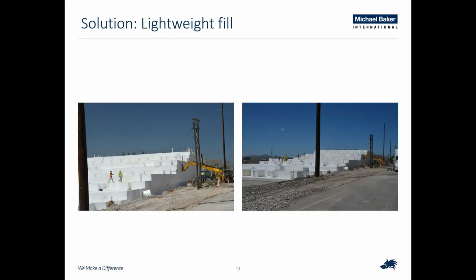This shows the geofoam embankments. So shifting the alignment helped mitigate those utility relocations, but the tall walls with ordinary fill would induce settlement on the adjacent existing utilities. And so geofoam approaches were proposed and designed for a zero net load, thereby eliminating the concerns for settlement on the existing utilities. And for those who don't know, geofoam is essentially just engineered styrofoam. It's very lightweight. And the zero net loading on the existing soils was accomplished by excavating out some of the soil that was there and thereby replacing the heavier soils with this lighter geofoam.